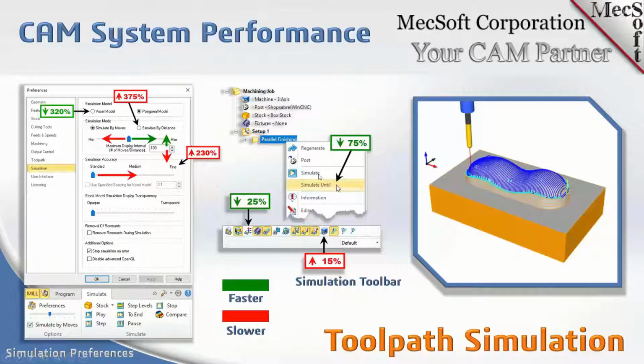Also be aware that if your operation is 12 operations down and you simulate until, it's going to calculate all the operations prior to that. It's not going to show them. It's just going to calculate them, get to the one that you simulate until, and that's the one that's going to show on the screen. So in most cases, if you just want to see the simulation, just pick simulate until, and it'll bypass all this other stuff you don't want to worry about.